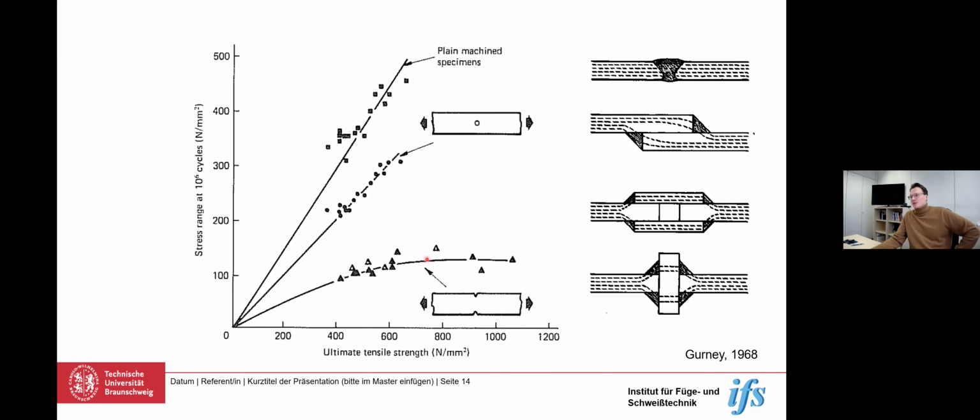Okay, and then what's also important when it comes to fatigue of these high strength materials when welded, we see normally that the fatigue strength increases with ultimate tensile strength. And that is usually the effect when you test base material. However, if you start to introduce notches, you have already a smaller effect when the notches are mild. But if welded, this effect becomes even larger, until a point where you almost have no increase in fatigue strength anymore with increasing material strength. And there is even a turn-off point where this may drop later.